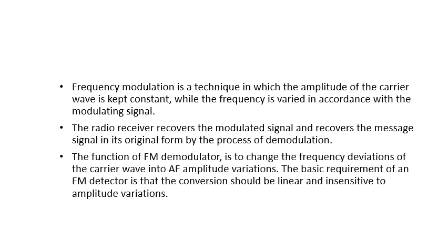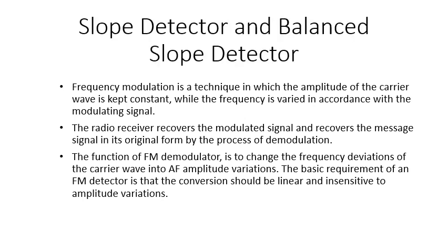So, the function of the FM demodulator is basically to change the frequency deviations that are present in the FM wave into the corresponding voltage variations. And the basic requirement in this process is that this conversion should be linear.